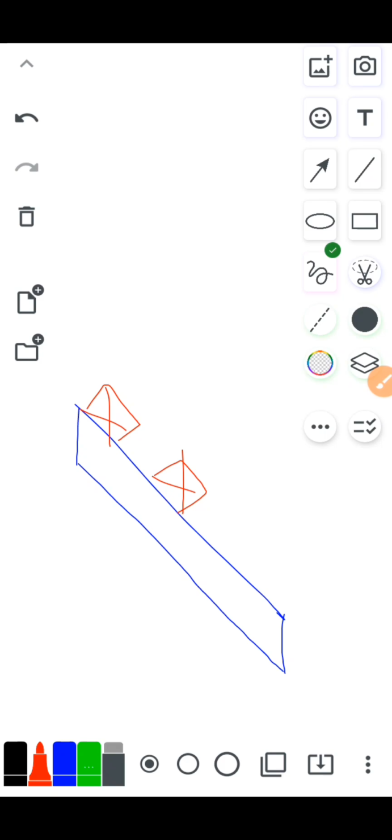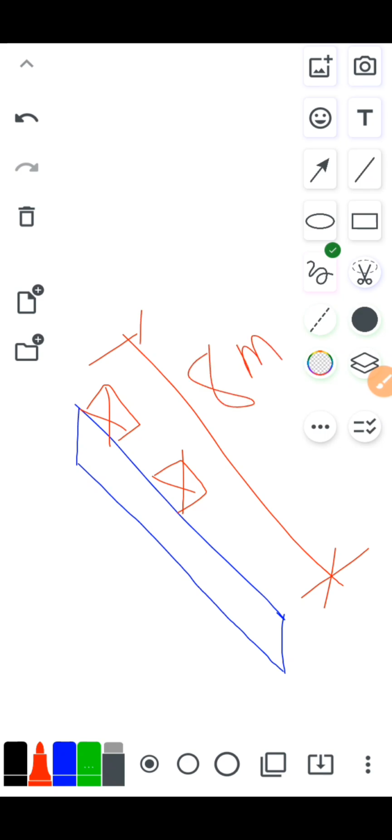Number one, we need the length of this rafter, along this rafter, that is from here to here. Let's assume we have 8 meters. We need to determine the interval between our rafters. Depending on, let's assume we are using 0.55 mm gauge of long span aluminum, the distance center to center should be about 750 to 800. So let's pick 750.